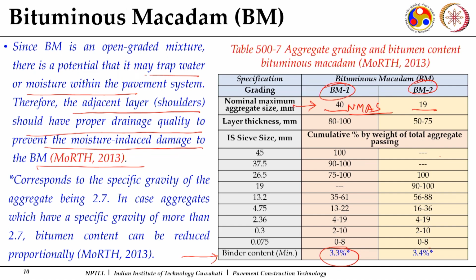of thickness. So there it says if you have this aggregate gradation, it is preferable to use 3. So already it is given that you go with this one, but this is for the most common specific gravity of aggregates we encounter. If the aggregate specific gravity is around 2.75, if they have a high specific gravity, then you can reduce the binder content. And if you have some colder regions where most of the temperatures are below 10 degrees centigrade, you may have to increase your binder content also. So that's why these mixes are called recipe mixes.